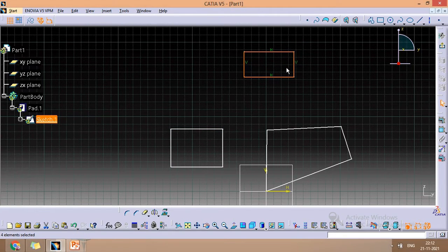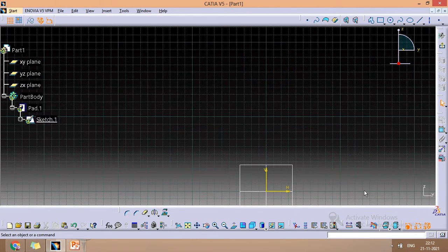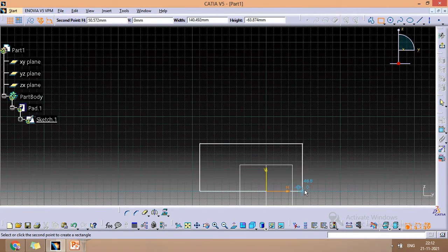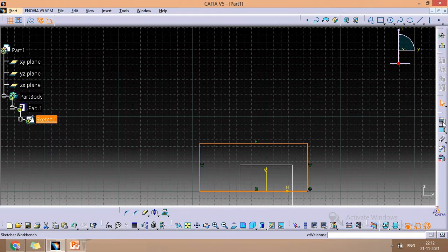We get this geometrical constraint while enabling the geometrical constraint. Normally we will create a drawing from the 0 0. If I draw a rectangle like this, the horizontal line on 0 0, the green line which is fully constrained, changes to a blue line.